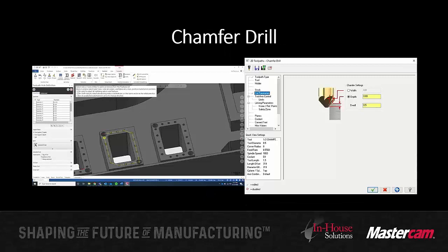Next would be the chamfer drill toolpath. The chamfer drill toolpath is essentially taking the place of what we would do in the past if we were going to chamfer this part: we would do a normal drill toolpath, and we would utilize the calculator within my linking parameter depths to figure out what's the final depth I want to hit based off of this tool and the geometry of my tool with my flat. The only downside of that is, in doing it that way, I can only toolpath for one size hole at a time.